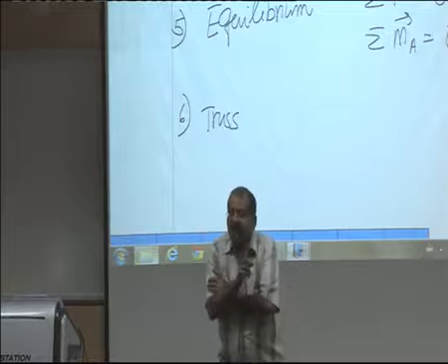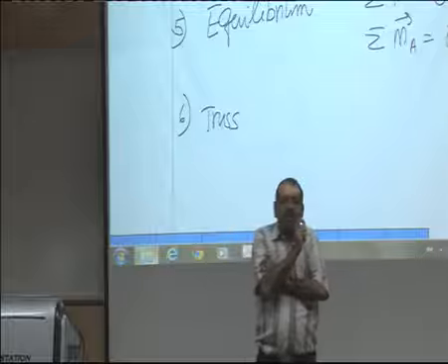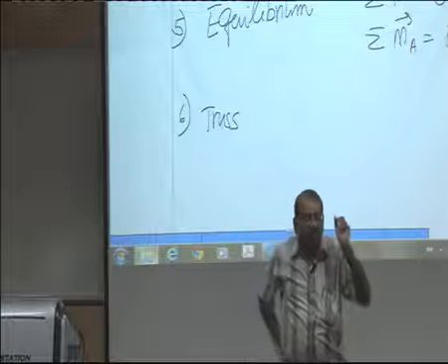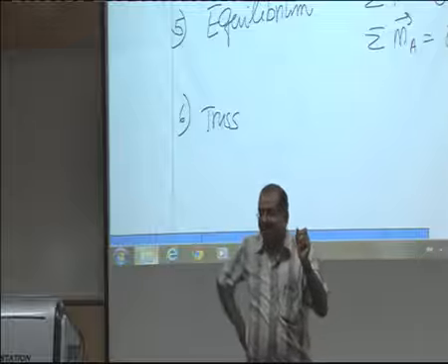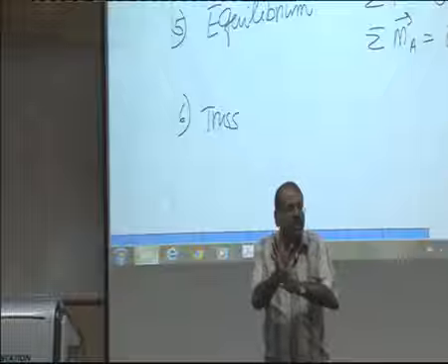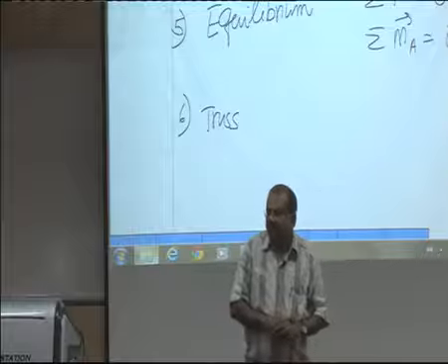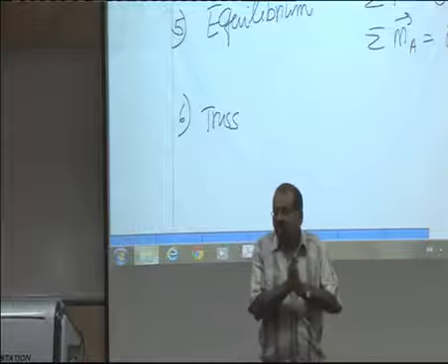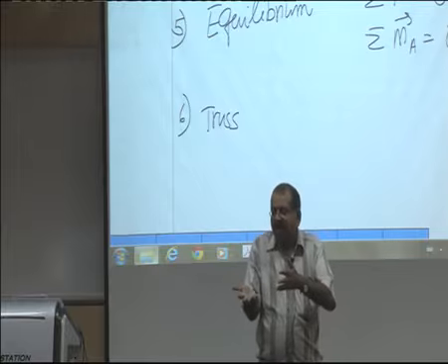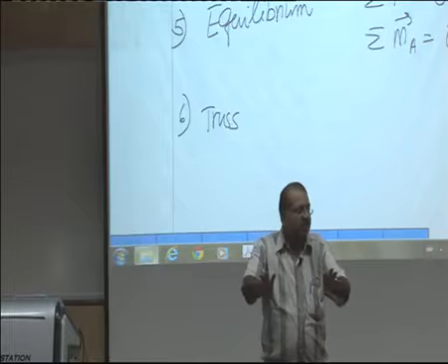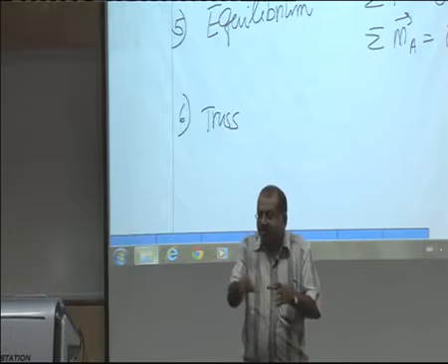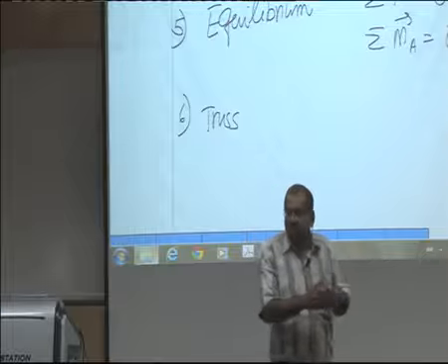Another thing we learnt was how to find 0 force members by inspection. By looking at the members and the loading, can you say some of these members are 0 force? You should be doing, and actually determining that. If I give you a loading and a truss, it should not take you more than 2 or 3 minutes to identify the 0 force members.